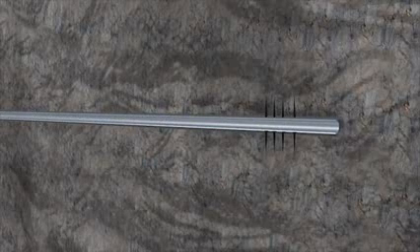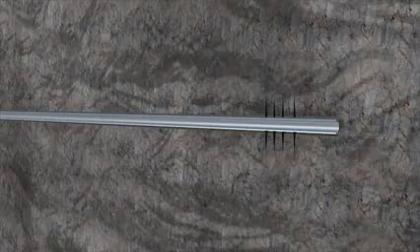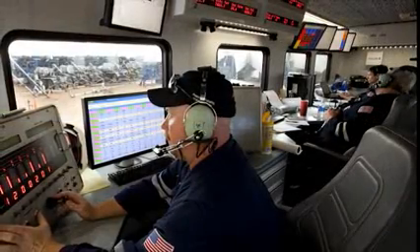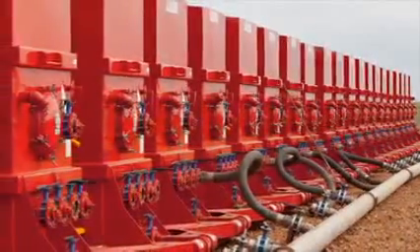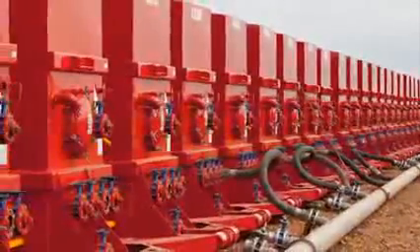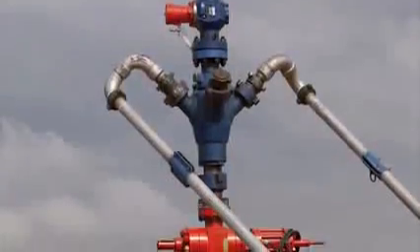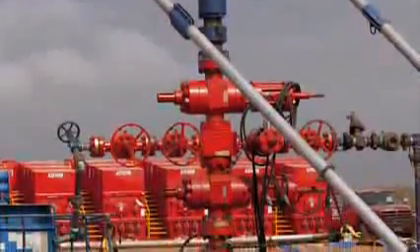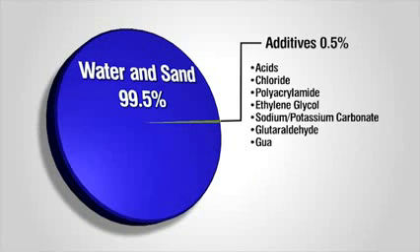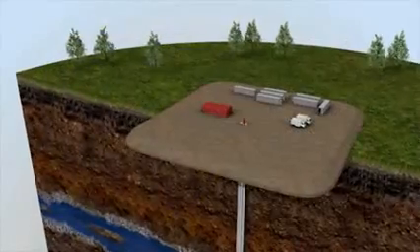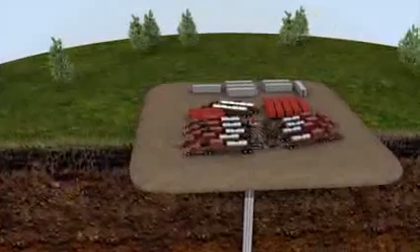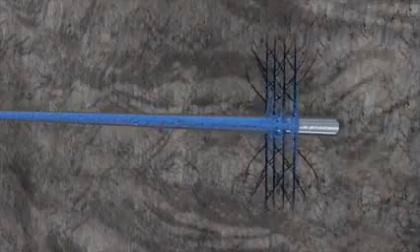The perforation gun is then removed in preparation for the next step, hydraulic fracturing. The process consists of pumping a mixture of mostly water and sand, plus a few chemicals, under controlled conditions into deep underground reservoir formations. The chemicals are generally for lubrication, to keep bacteria from forming, and help carry the sand. These chemicals typically range in concentrations from 0.1 to 0.5% by volume and help to improve the performance of the stimulation. This stimulation fluid is sent to trucks that pump the fluid into the wellbore and out through the perforations that were noted earlier. This process creates fractures in the oil and gas reservoir rock.